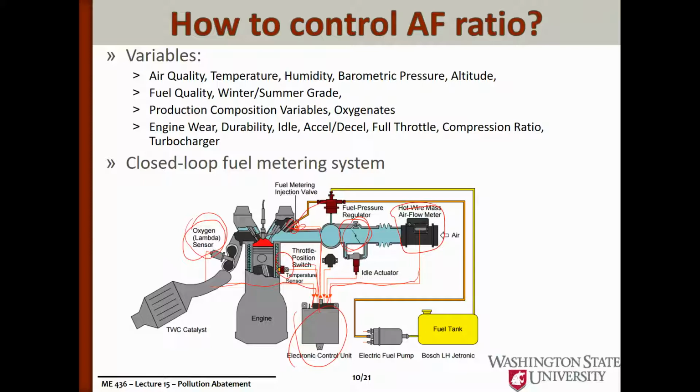So as part of introducing the catalytic converter, that was the same time that we finally started moving, on a widespread scale, to using electronic control units and fuel injection rather than carbureted engines. They go hand in hand, they help each other. The catalytic converter would not function at its best in a carbureted engine. We need this additional control of the air to fuel ratio.